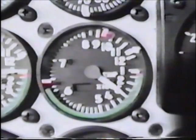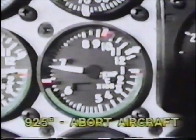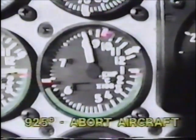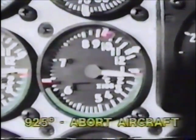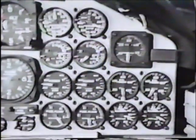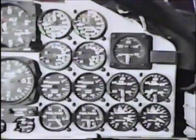Exceed 925. If the EGT ever exceeds 925, you must abort the aircraft. After the EGT stabilizes, continue with the checklist. Engine instruments, check. Ensure that each instrument is within specified limits for idle RPM.